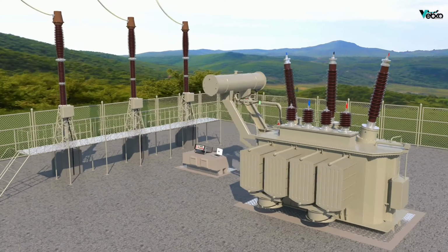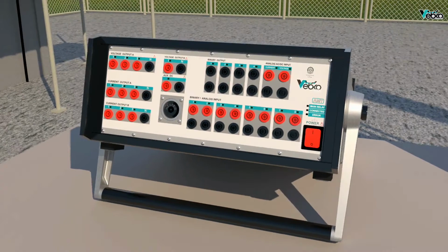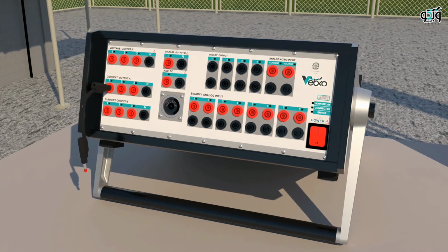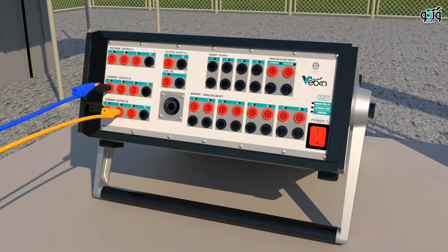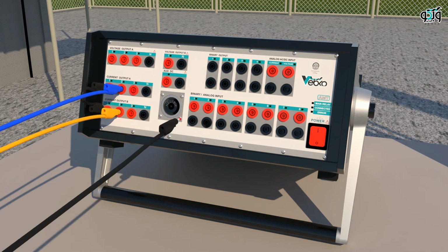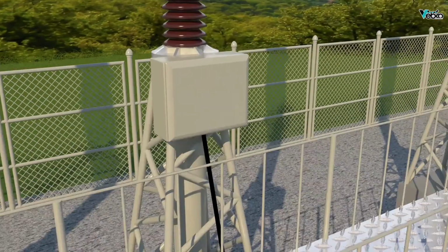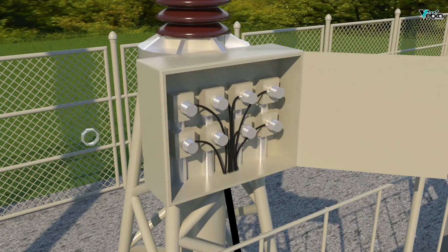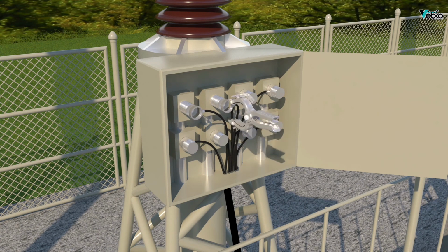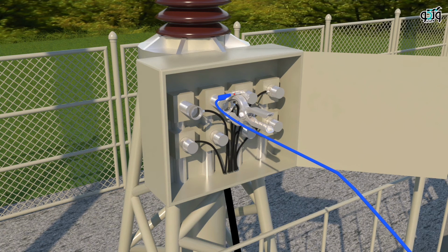To perform this test, in the first step, the CVT must be separated from all elements that are used for transferring voltage to measurement devices. In this wiring, jumper IA1 and IB1 current outputs and connect IA2 and IB2 to the CVT voltage transmission path. Also, to measure the AC voltage, binary analog input 1 must be connected to the test path a little further from the current injection connectors.